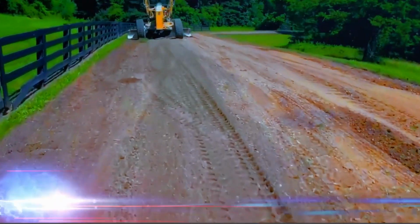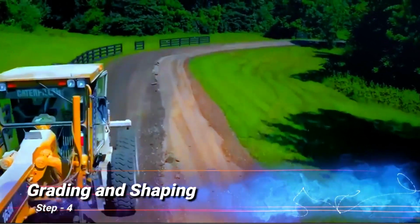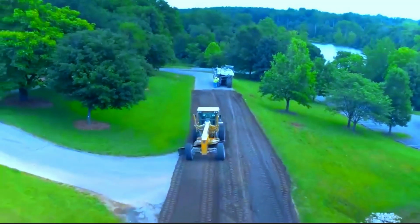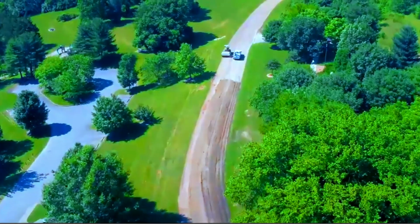Step 4. Grading and shaping. Once mixed, the stabilized material is graded and shaped using a motor grader to achieve the required profile and slope. Water may be added if necessary to maintain optimum moisture levels for compaction.